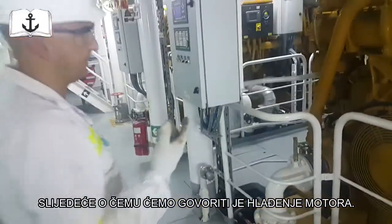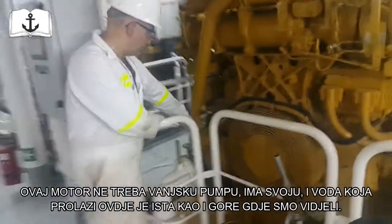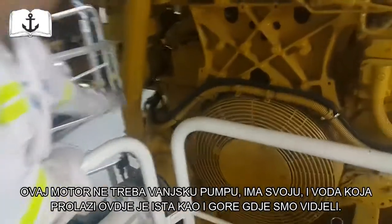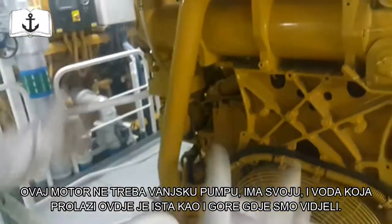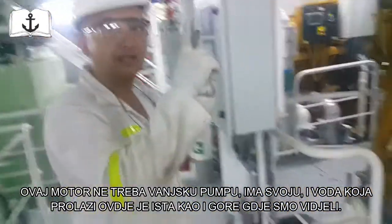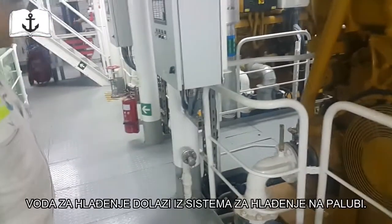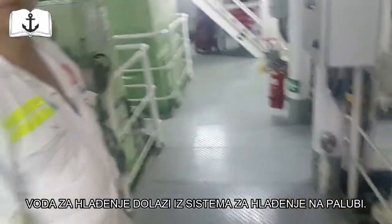And the thing is that this engine doesn't need any external electric pump. It has the pumps here, and this pump is cooling all the body of the engine. And this water, what we mentioned before, is going to the deck, where the battery of the radiator is. So this water is coming from our cooling system on the deck.